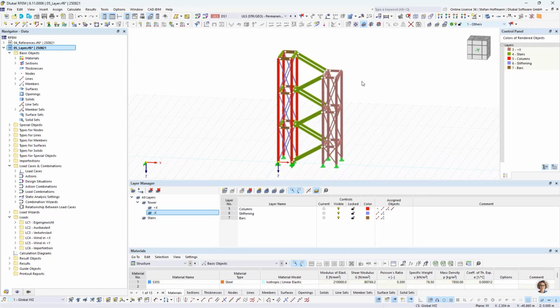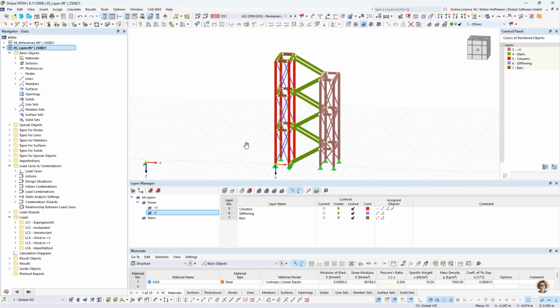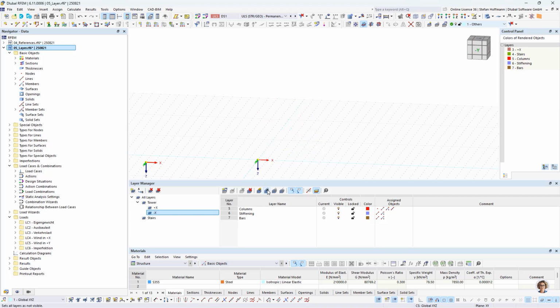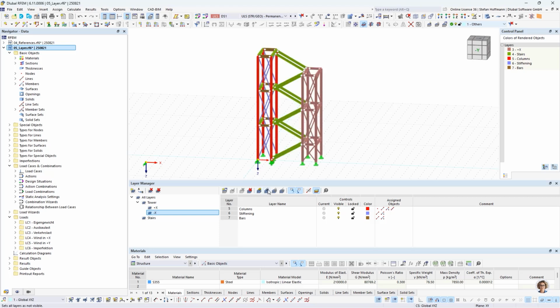A big purpose is that, of course, the grid, which is shown in the background, and all the guidelines are not layer committed. So usually only objects will be put into the layers. And it is quite good that you can disable the view, so you can hide all layers, or you can hide single layers, and you can also, of course, choose the command function to display everything in the background or not.